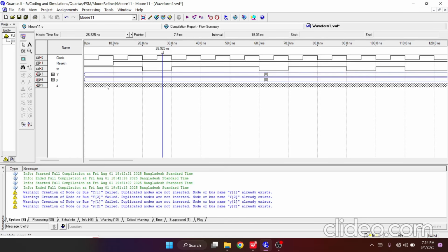But you need to keep in mind that first you have to apply the clock, then depending on the clock period, you will give the input to the rest of the input pins. So the reset n will remain low for one period, then it will remain high for the rest of the time, and the W values are applied for one whole clock period.